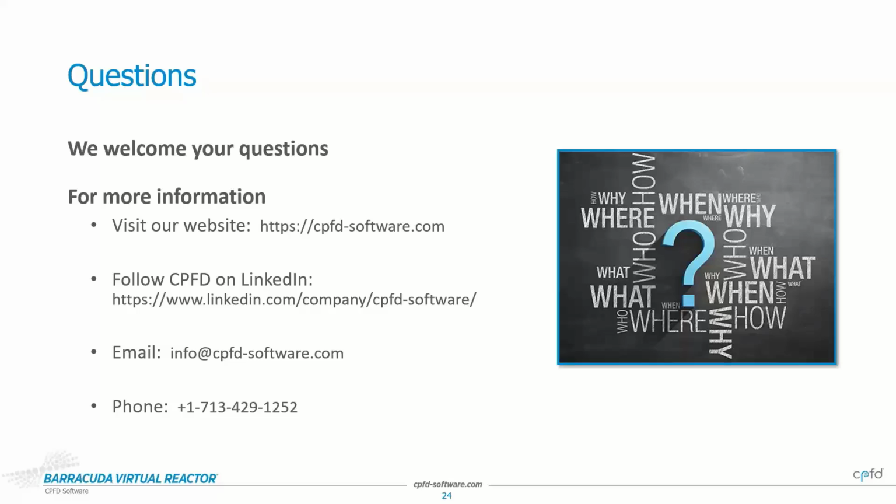Okay. Kind of related to that, I see this question. Can you show which cells are restricted by the volume ratio setting with Tecplot? Yeah, and in this case, you can't, currently at least, right? With this release, we've allowed you to enable this feature, but there's no visualization data output that would be able to indicate where this is happening or to what extent. So I think that's a very valid feature request for the future. But currently in this release, it's not possible.